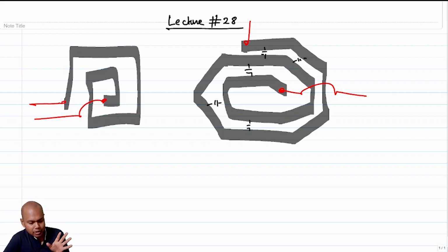So if you are looking for inductances with lower loss, then it is better not to have very small spirals inside, and maybe have one or two big turns on the outside, and let it be. Okay. Now the problem with that is that you take up a lot of area. Now that's a design call, right? Whether such an area is acceptable or not, right?